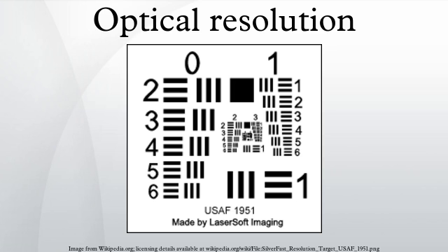The best visual acuity of the human eye at its optical center is less than 1 arc-minute per line pair, reducing rapidly away from the fovea. The human brain requires more than just a line pair to understand what the eye is imaging. Johnson's criteria defines the number of line pairs of ocular resolution, or sensor resolution, needed to recognize or identify an item.